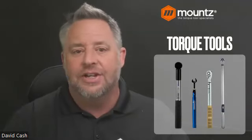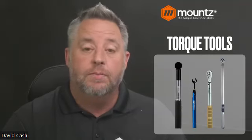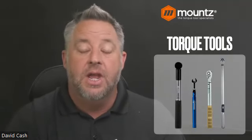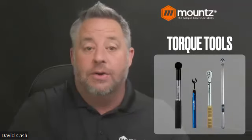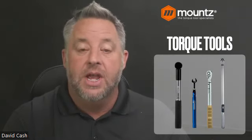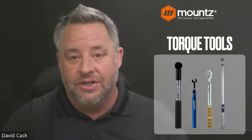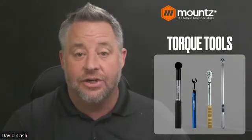And this acts just like a screwdriver would as well. As we pull on that wrench, it's going to cam or slip once it reaches a certain value, just like the screwdriver. And that will allow us not to add any additional torque to that actual assembly. As we pull it, it's going to completely slip and then it can just keep going around and around, but it is not going to give us the ability to add over torque to that fastener.